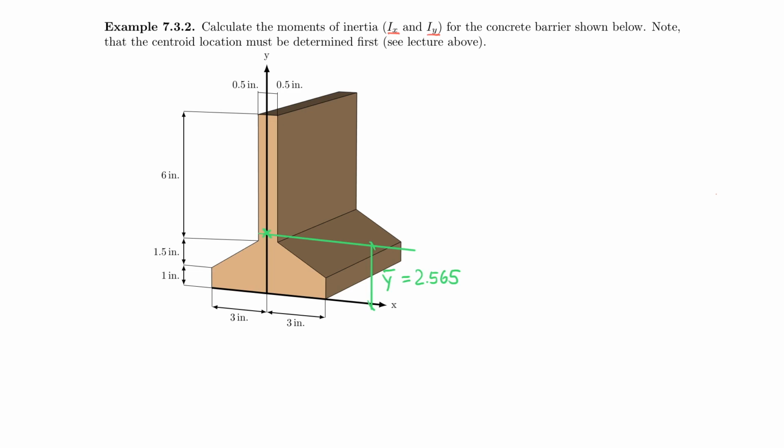All right, like we did in the centroid lecture, we also have to section our element into area elements that are of known shape and known geometry. And I believe we did it so that the horizontal part on the bottom is continuous. So I'm going to do that here as well. And then I have my different areas. I believe this here was our area 1, so I'm going to call that A1. And then I have an area down here, which I'm going to call A2.